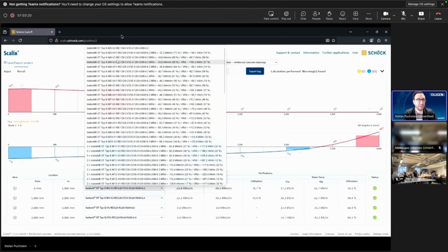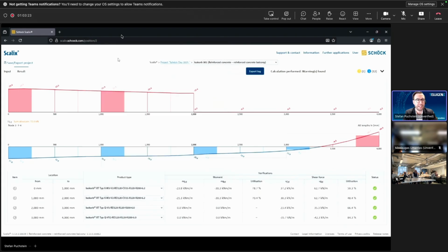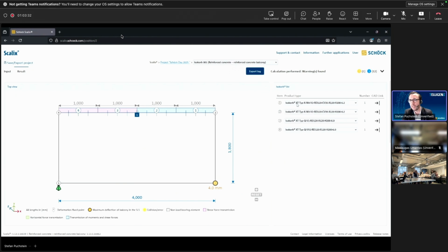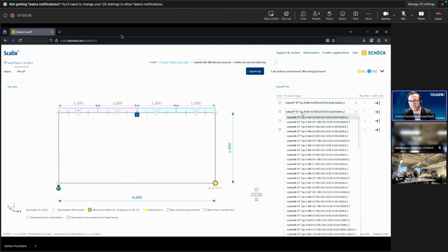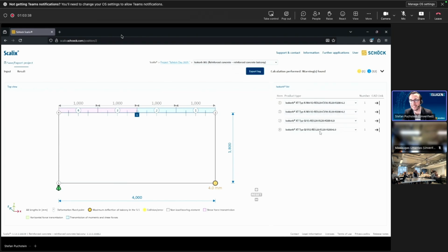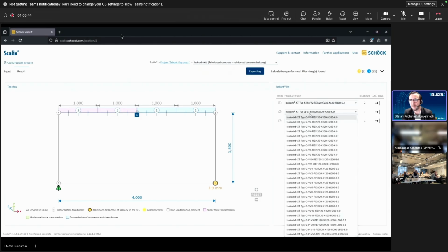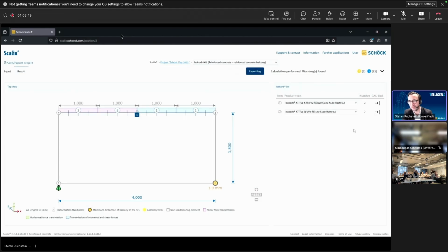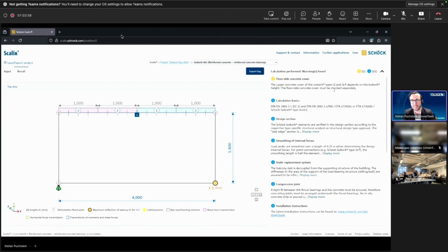Here, you can swap elements to use any different load stage if you want to do so in the process, and recalculate all the static proofs. As you can see, you can do it right up there as well for all the positionings, in this case for number 2. We chose the same load case as in position number 1 and for position 2 as well. So we are left with 2 different element types in this instance, which might make it easier on the construction side, but of course isn't the most economical solution if you have to look at that.